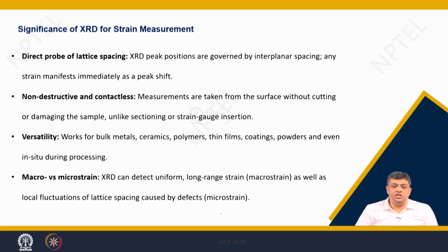X-ray diffraction is a commonly used technique for strain measurement. As we have seen, it is a non-destructive method, it is contactless and it is very versatile, and you can actually differentiate between the macro and micro strain, and that is a beautiful advantage of this technique.